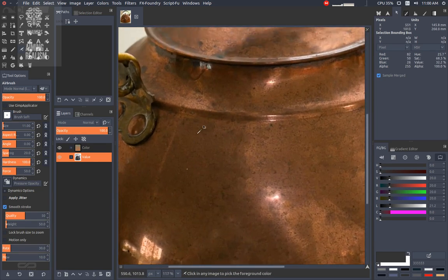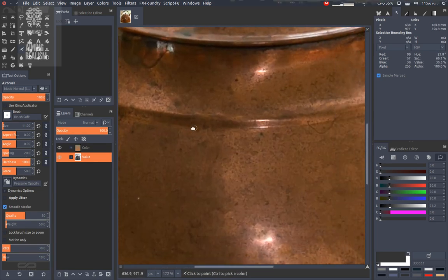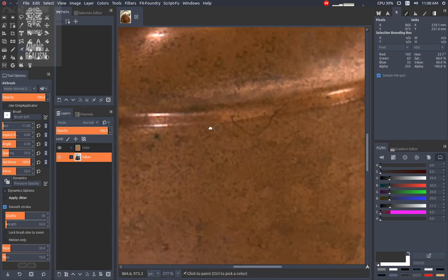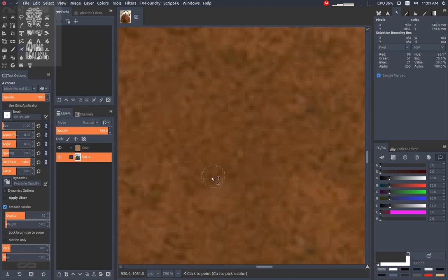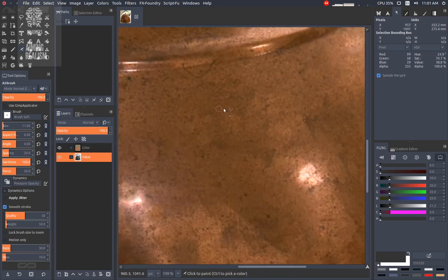And to me, that's the secret. It's really to try to isolate some tiny effect. For example, you have this shape here, but you have some dark parts at the corner. So how can you replicate just that in Blender? And when you find it, you put it into a shader or node group or whatever, and you can recall it after, mix them with a mix factor on a math node, and you will be able to create some really interesting stuff.